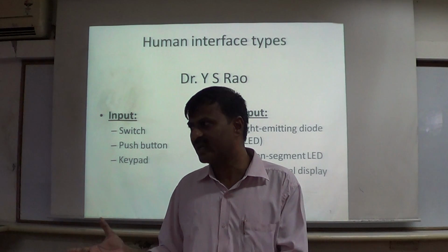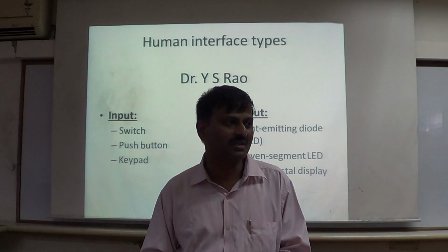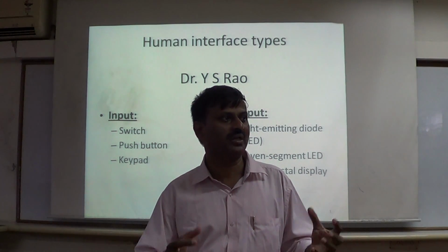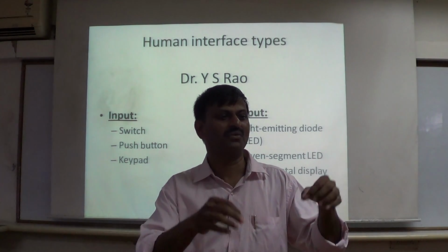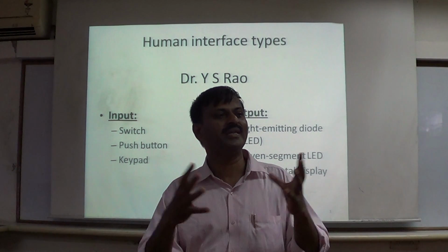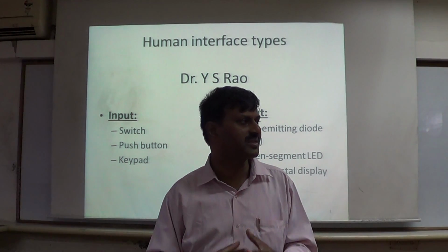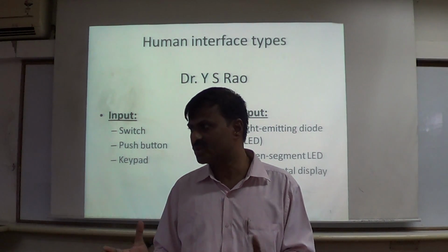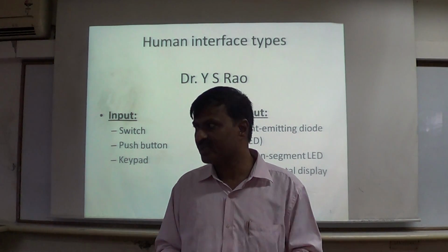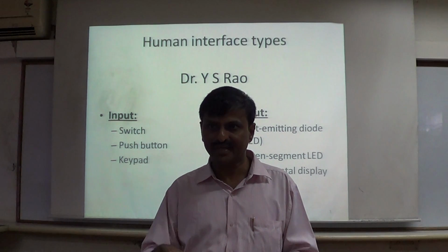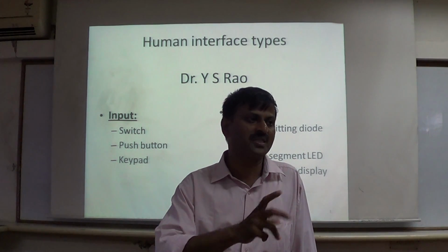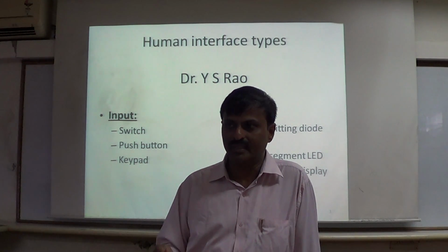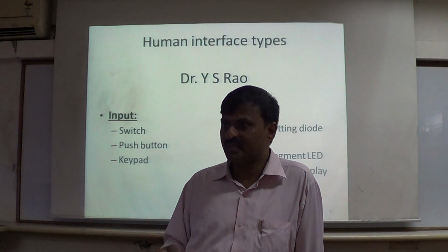The software can be either open loop or closed loop. But as I was telling, there is always a risk in going with an open loop system, because it is not possible that whatever command you have given actually happens, because your environmental conditions won't be the same always. There will always be some dynamic loads which will have an effect on your motor, so the displacement will differ. Some backlash will always be there. So that has to be measured by some sensors.